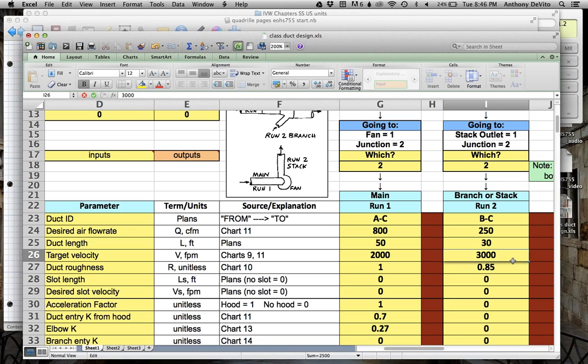Yeah, I look at the chart, and on the chart it says, on chart 10 that you have over there, well, I'm sorry, chart 9 rather. I go to chart 9, and I got mine mixed up here. For a fine dust or powder, you need 3,000 feet per minute. For very, very fine, very light dust, 2,000. For medium dust, 3,500. For coarse dust, heavy dust, 5,000.